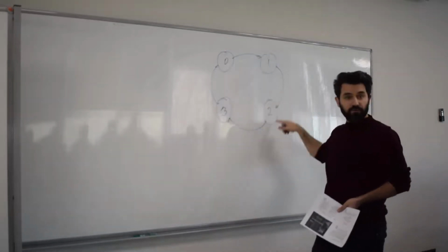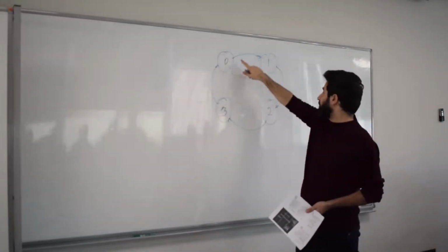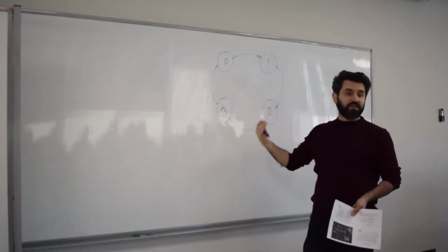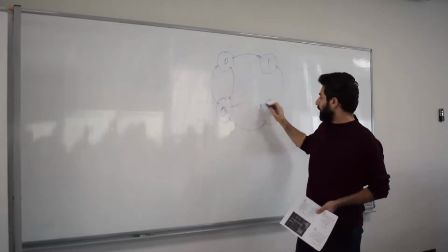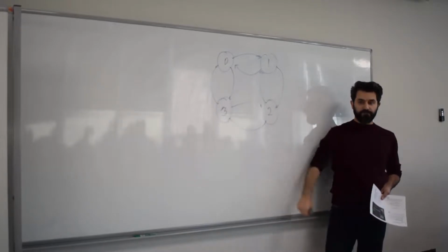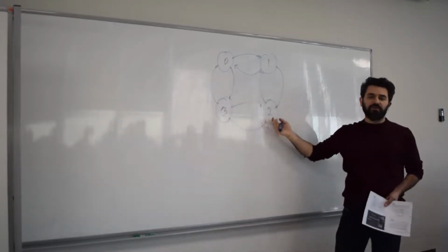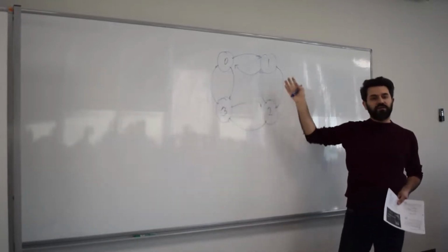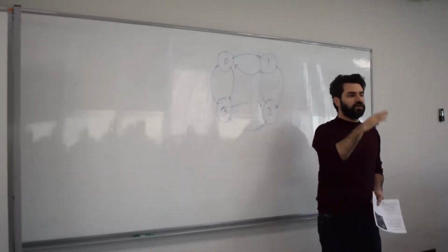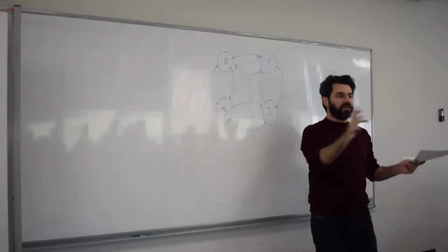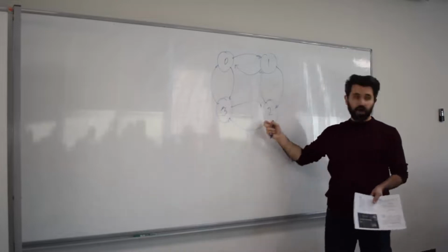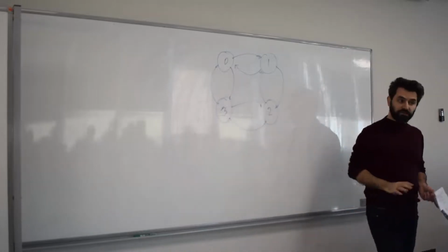This is an up counter because it actually raises. You see, it goes up to 0, 1, 2, 3, so the value increases. Or you can decrease the value by going in the counterclockwise direction, right? That's going to be the down counter. So you know how to design this, because if you're given the state diagram, you know how to go to state equations, state tables, the columns in your truth table, and then K-maps, and then the circuit itself, right? You know the process. So that's why, as I said before, it's not something new to you.